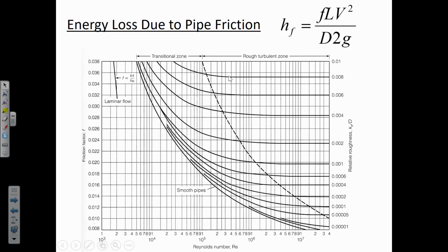And so that's called an implicit equation or an iterative equation, where sometimes the unknown is on both sides of the equation and you have to guess one part of what's happening, and then gradually you'll iterate and converge on the correct solution through a series of guesses and improved guesses. And that'll be a big part of the processes that we learn in hydraulic engineering, is when there are too many unknowns, guessing one of them and then converging to the correct solution.